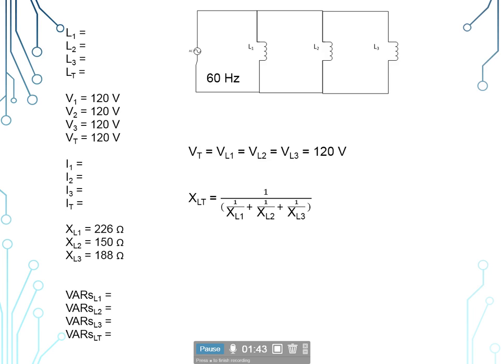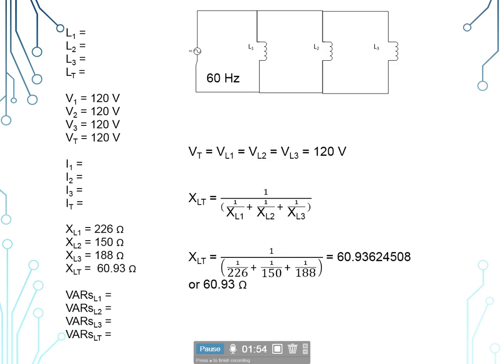And we populate X sub L1 with 226 ohms, X sub L2 with 150 ohms, and X sub L3 with 188 ohms. It'll give us 60.93 ohms. Now really in reality we could call that 61 ohms, we could call it 60 ohms, because again our calculations are a baseline that we use to compare, are we in the ballpark. It's kind of like horseshoes, close does count.